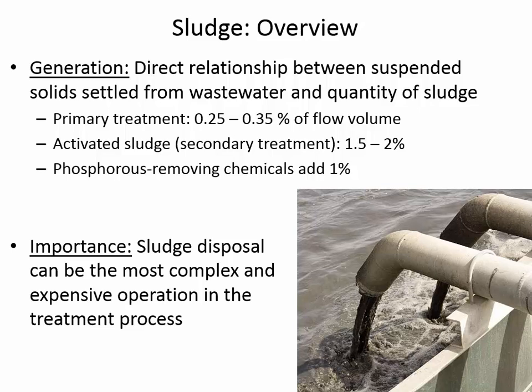That's what we're going to spend most of today talking about: sludge. There's a direct relationship between how many solids we're removing, the amount of BOD that's removed, and sludge. You've calculated P sub x, which is the mass of sludge produced. That's on a dry basis. But as I pointed out in the last part of the secondary treatment problem, sludge is usually mostly water.